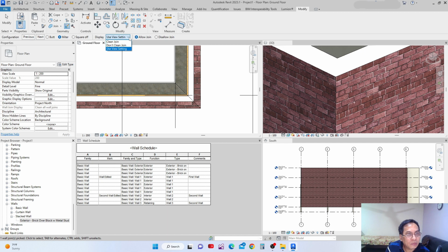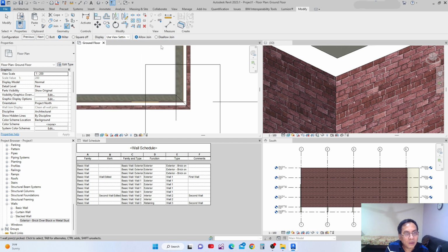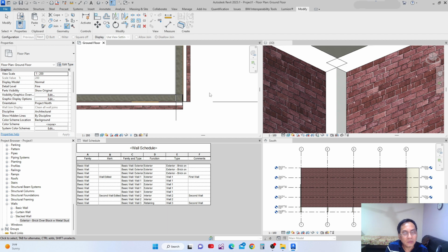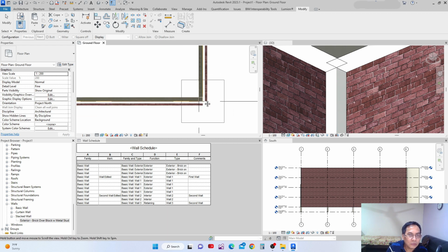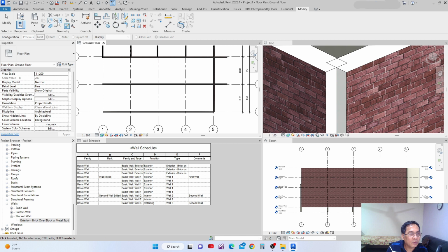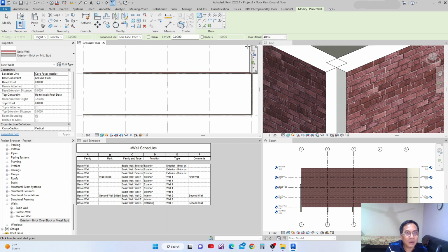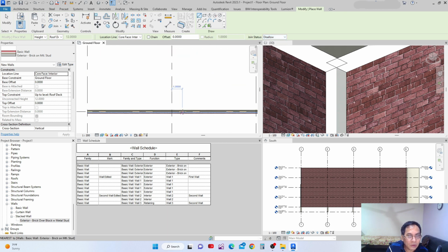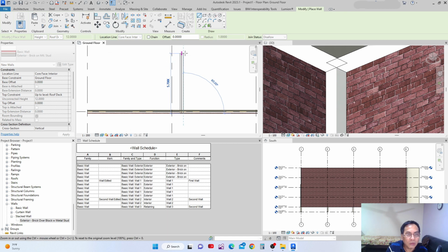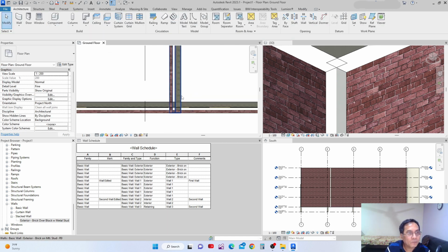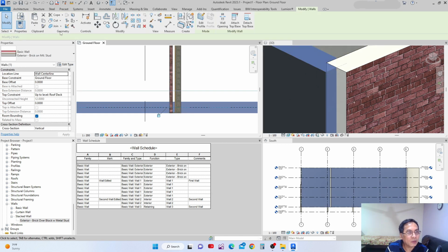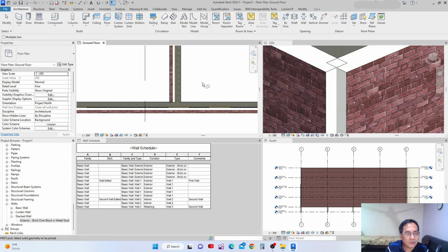There is a view setting down, chain, clean, don't clean, and then another thing, allow joint. If I click this allow joint, see, there will be no joints. And if I'm going to create another wall, I want to create another wall, and then I remove this. I just make this allow joint, and I make a wall. They are not joined. I can join them again if I go there and go to join geometry, just select this and there, and now they are joined.